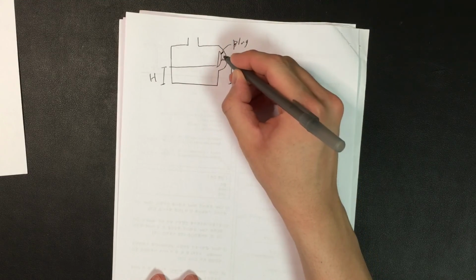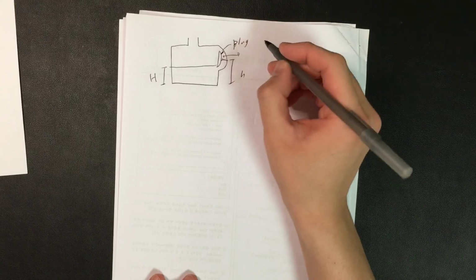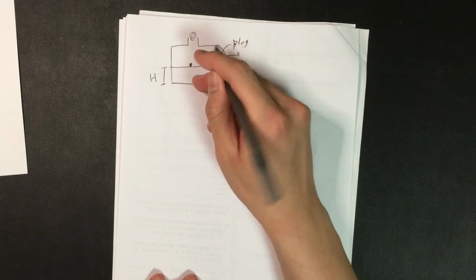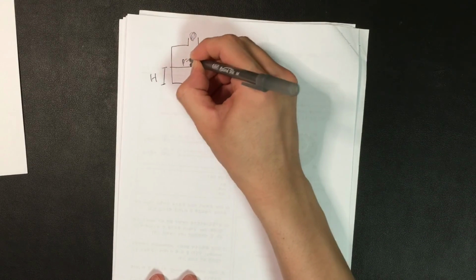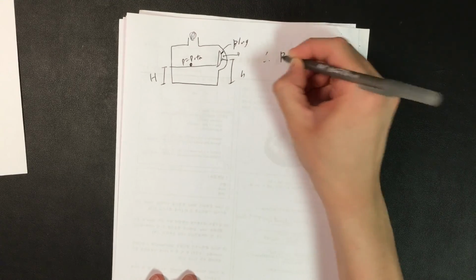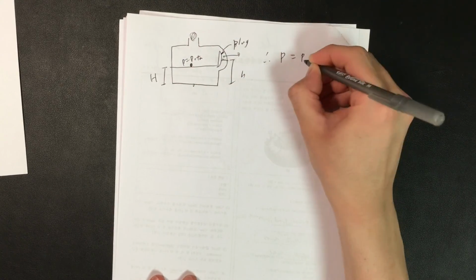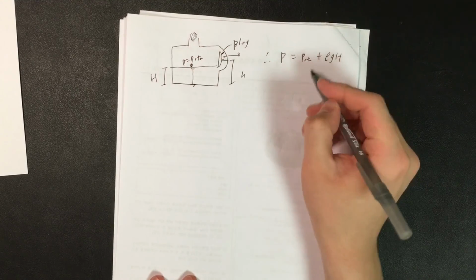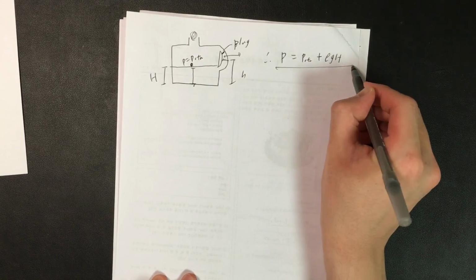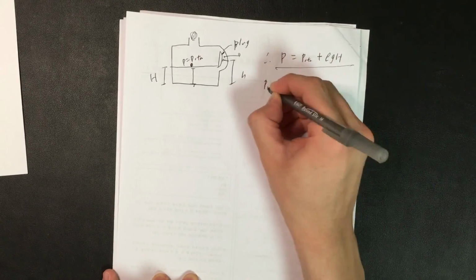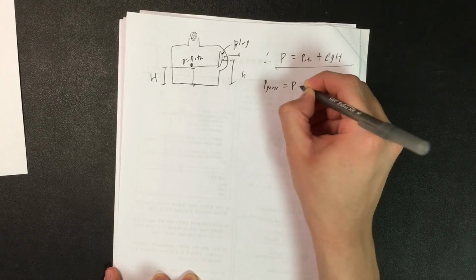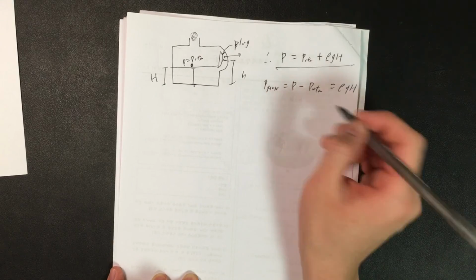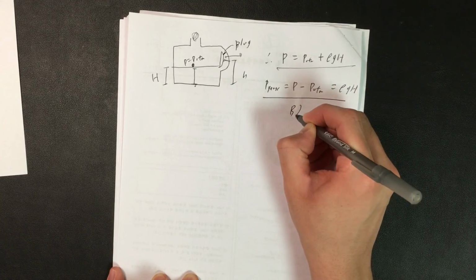Now, because of this plug, the pressure inside here is not necessarily atmospheric pressure. But since this part of the jug is open, pressure at the surface of this milk here equals the atmospheric pressure. And therefore, pressure at the bottom is simply P atmosphere plus rho g big H, because the distance here is big H, and from fluid statics, this is the form of pressure as a function of height. Which means the gauge pressure, which is defined as pressure minus the atmospheric pressure, is simply rho g times big H. And from the answer choices, this corresponds to answer choice B.